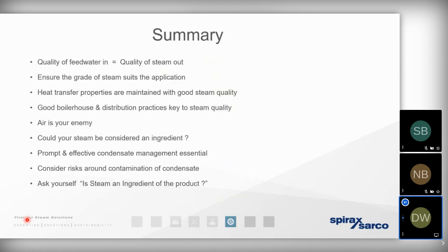When we're talking about a good condition of steam, typically we mean that the steam suits the requirements of the application, and that can vary depending upon whether we're using steam for a basic instantaneous plate heat exchanger, or whether we're using the steam directly injected into a pharmaceutical or a food product, for example. So we know we need to keep the steam at a high condition, at a good quality for heat transfer purposes. Typically, we're talking about keeping the steam as dry as we possibly can and free of air. It's only by doing so that we can guarantee that we're operating close to the steam table values.